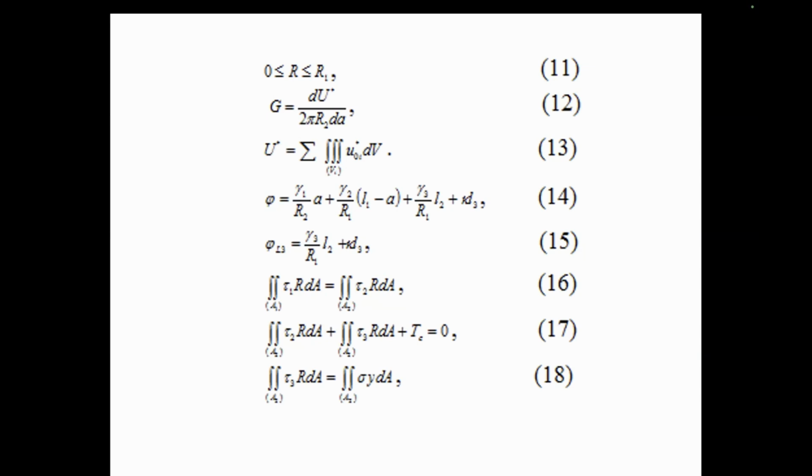The strain energy release rate for the crack is extracted from the complementary strain energy in the shaft by applying equation number 12. The complementary strain energy density in a shaft portion is extracted by integrating the physical laws 3 and 4 with respect to the corresponding strain.